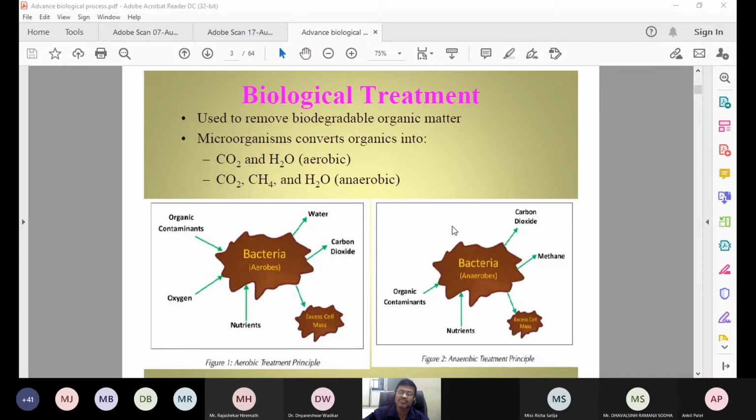And you know, BOD is initial minus final. So in the first bottle it is 8 minus 5, that is 3. In the second bottle 8 minus 3 is equal to 5. So if you have done that dilution 100 times, then the BOD is 500 milligram per liter in the second, and in the first it is 300 milligram per liter.